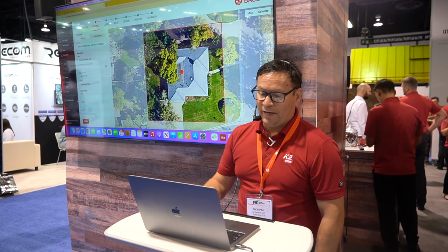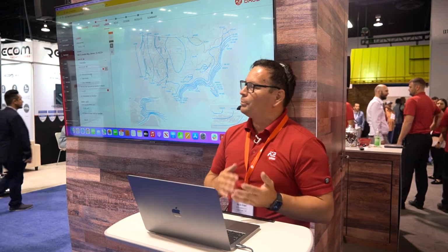So I'm going to go ahead and hit add the project, and then it's going to take me over to the wind conditions of the actual area based upon the weather conditions of that zip code. So it knows that we're going to be going there to Denver. We're going to go ahead and select its wind exposure as a category B, suburban dwelling. This information will also go over to GreenLancer, and we're going to put in a wind speed about 120. After that, we're going to click on its average snow load of 30 PSF, and we're going to click continue.